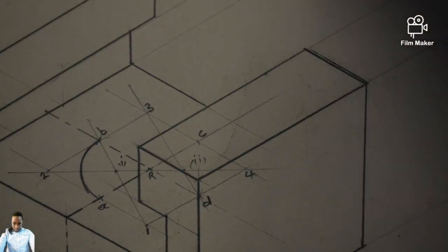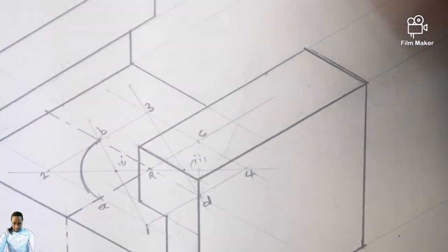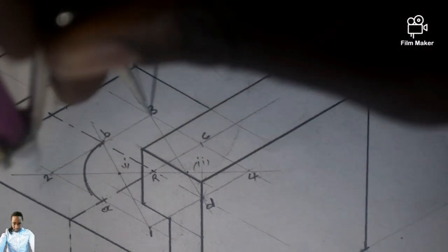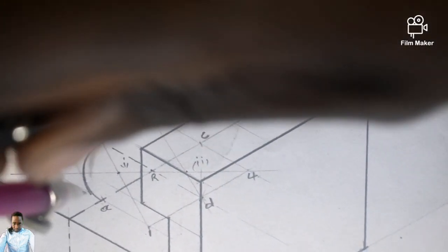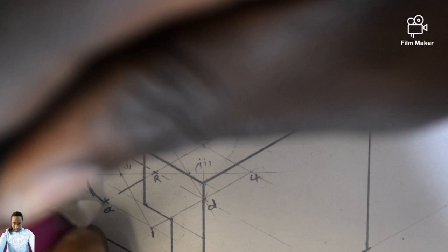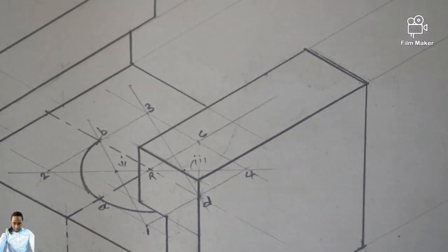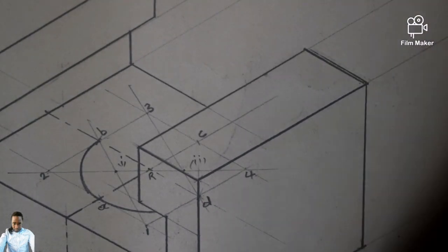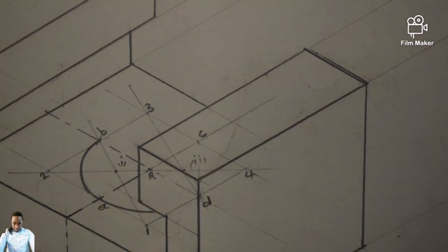So now to get this side, we're supposed to place the drawing compass at point 3, further extend to what? To point A, isn't it? And this arc of yours must start from A to what? To D. So 3 to A. There you go, and it's supposed to be dark till here, because from here going in is now the bottom part of your workpiece.